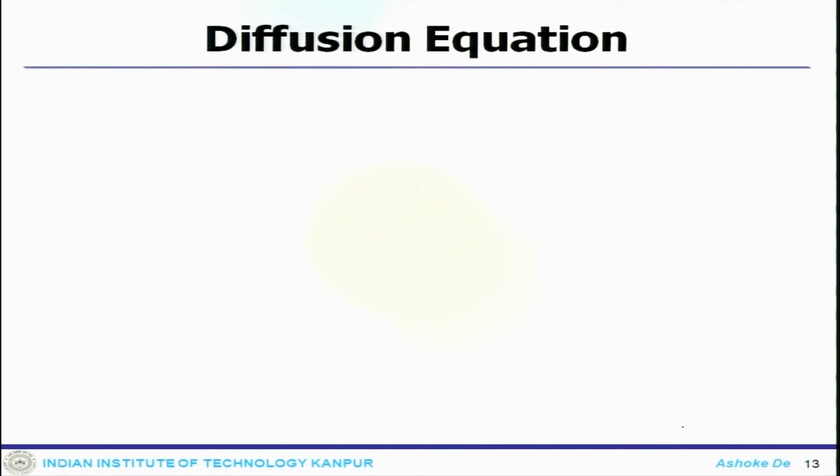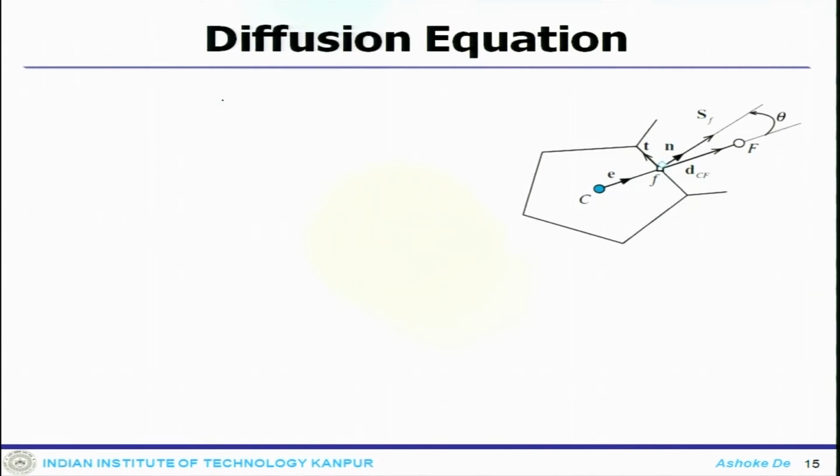Okay. So, once we go to the unstructured system, these are non-orthogonal unstructured grids. First, we consider the non-orthogonality, and to do that, the essential component would be the gradient calculation. So, let us consider this system for non-orthogonality. Let us consider one particular element C, in a non-orthogonal mesh.